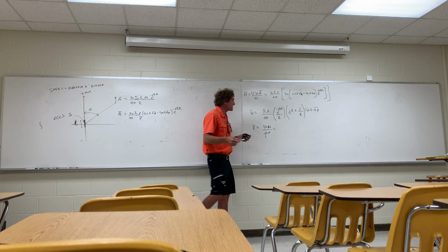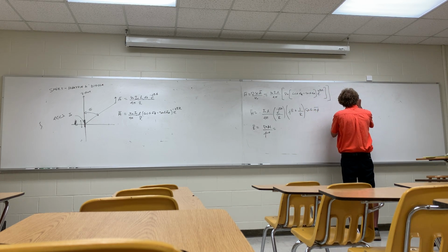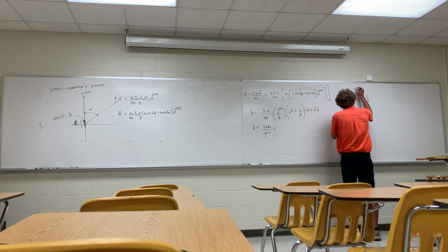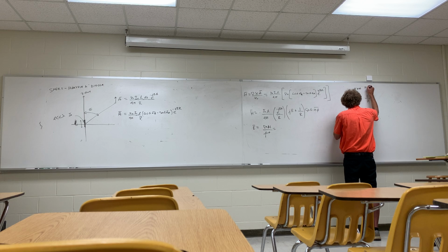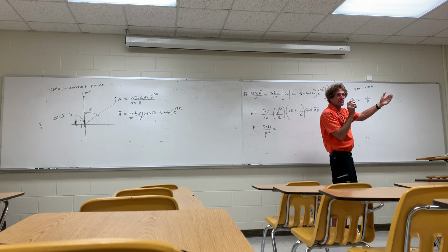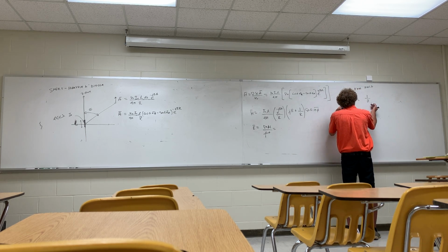What they do normally is they say this. They're going to take the magnitude of that and set it to the magnitude of this. So they say beta is equal to 1 over R. This defines the far field. Now, it's not a hard barrier. It's not like up to there, it's all near field, and from there on, it's all far field. That's the point where all of a sudden, most of the energy and power will be radiant in the far field. So this is how we do it. So then I take 1 over this, and I get R is equal to 1 over beta.